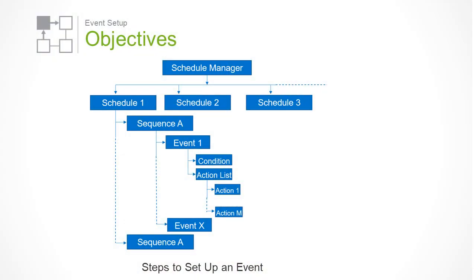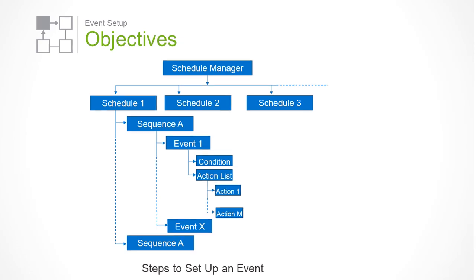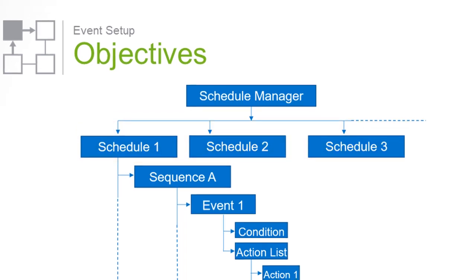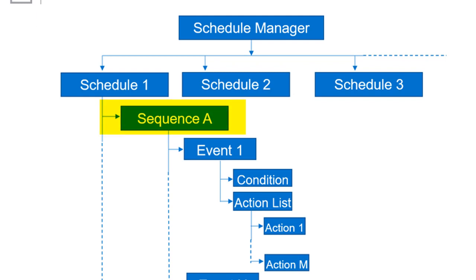Now we are going to walk through how to set up a basic event in Aspen Hysys Dynamics. We will add a new event schedule in the Schedule Manager to set up an emergency scenario that may include several sequences. Then we can add a new sequence to configure the actions to predict the flowsheet behavior. The sequence can be a collection of actions on the unit operations.